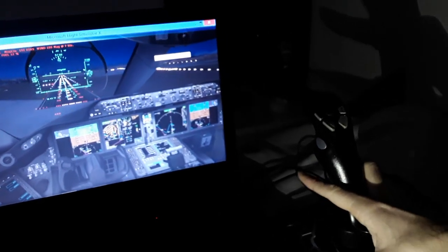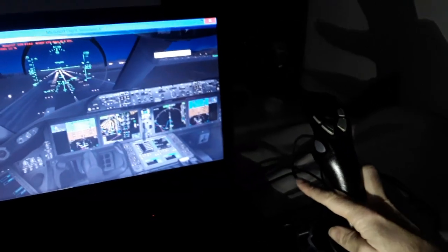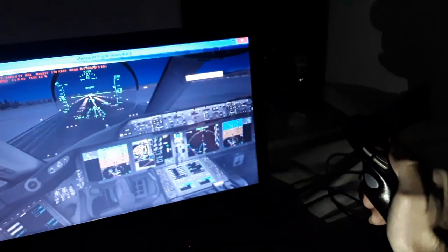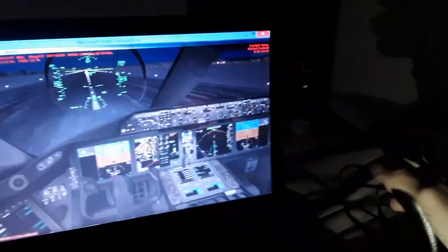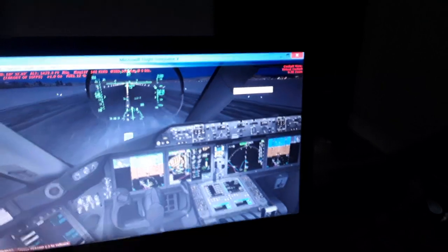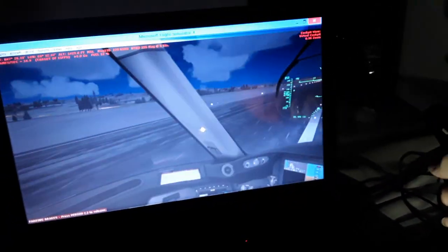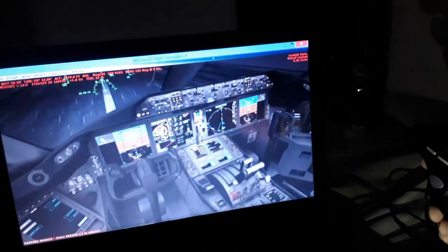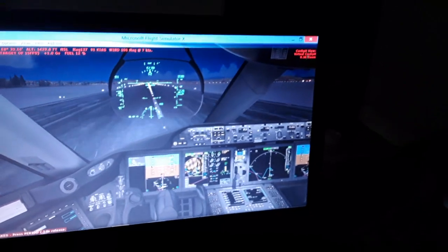And we are very close to the flare of the aircraft. We align and we have over here the flare, as you can see. So we flare, beautiful flare, beautiful touchdown, parking brakes, idle thrust and thrust reverse over here for the aircraft to slow down on the runway. As you can see, we have a few more seconds to slow down, align with the center line with the rudder pedals. So you can see we're slowing down over here.